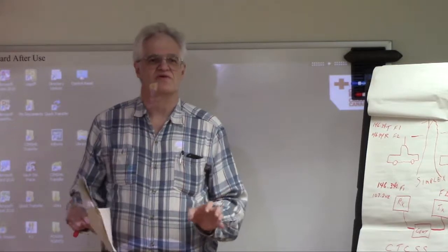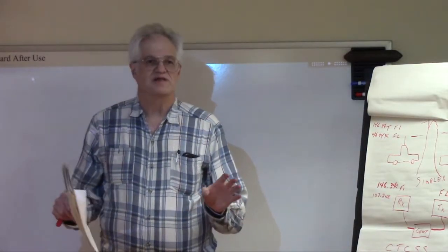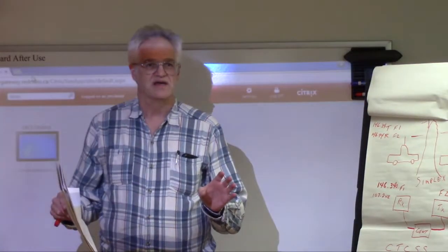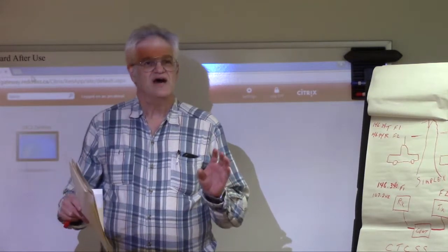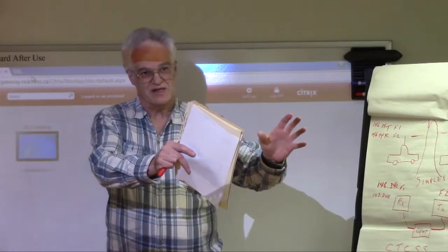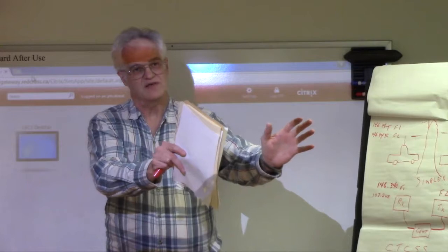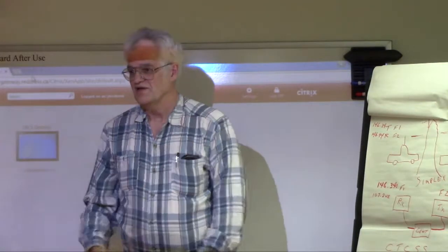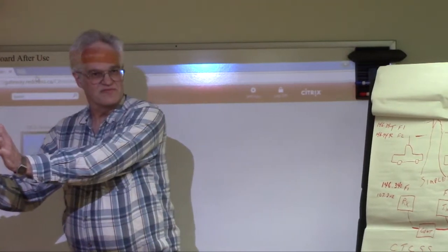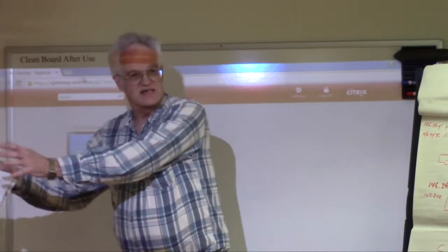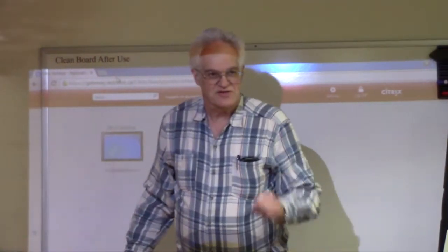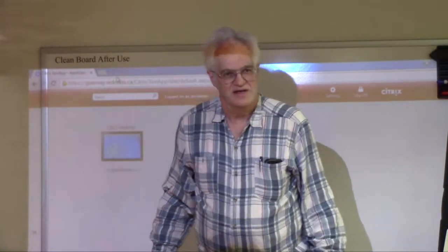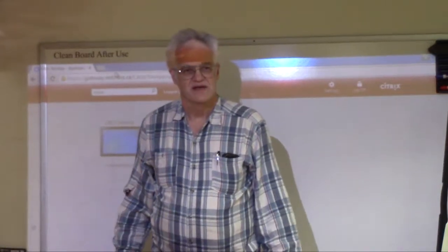Like in the commercial world, you might have more than one company using the same frequency. So what you would have was this company's people, their radios all be set to use this tone, and you could have another group of people on the same frequency using a different tone, and neither one would hear each other's conversations. Okay. So there's less interference.